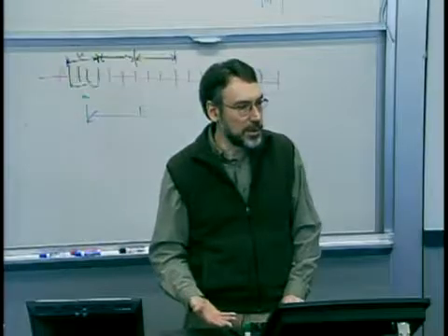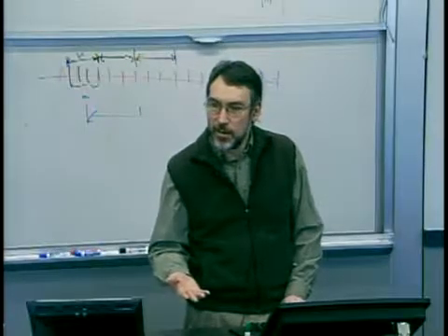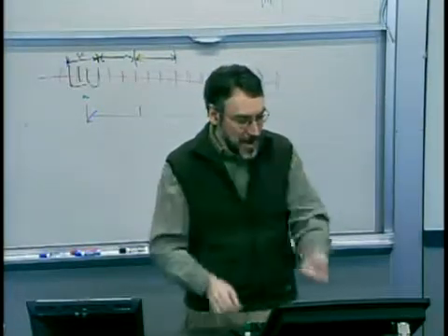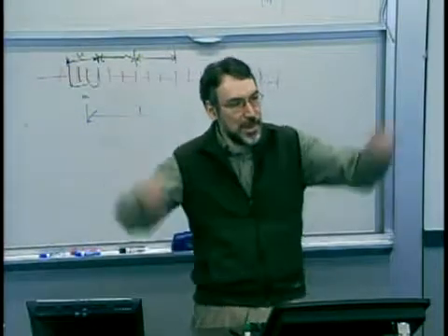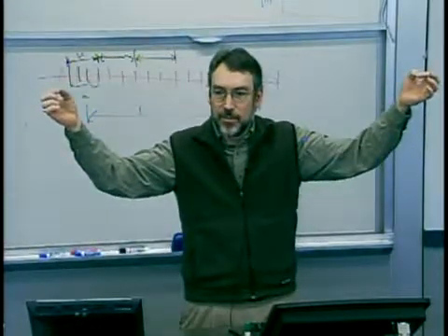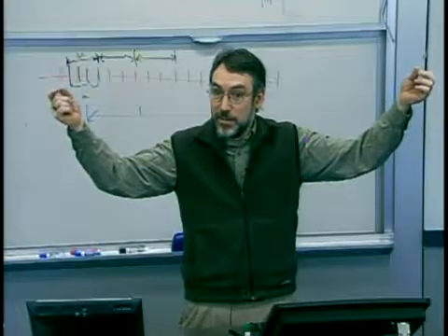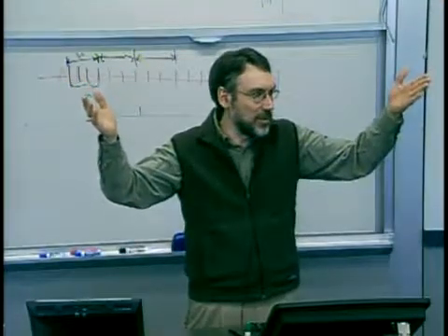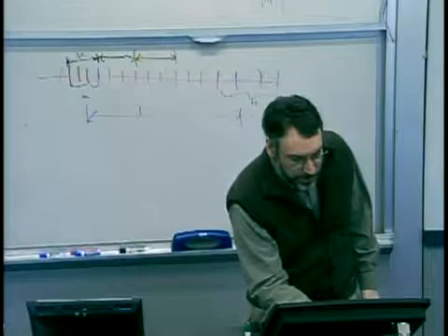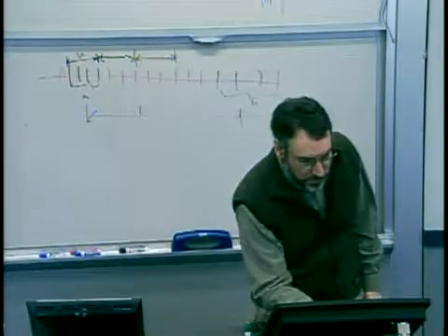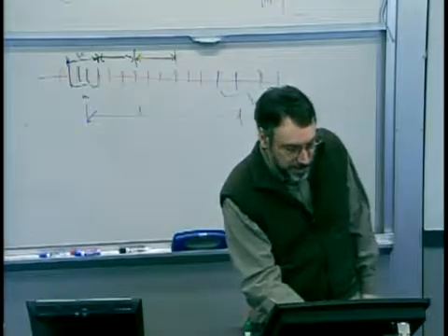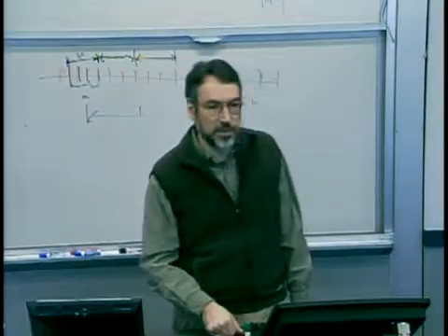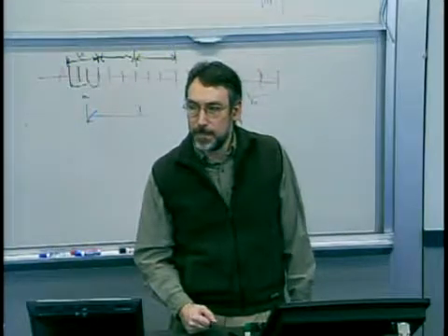Here's another situation. What's changed here? Now, in this case, my spread is much smaller. I've got a tighter distribution. And in fact, my upper spec limit to lower spec limit is basically 12 sigma. That's great, right? So that's a CP of 2. Now, I'm still off-centered. I'm mistargeted. And so in this case, my minimum distance from mean to the lower spec limit, that is the smallest distance, is still 3 sigma. So when I divide that distance there, I get the CPK of 1. Okay.